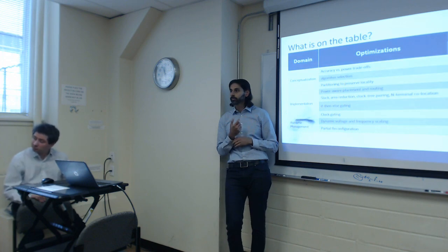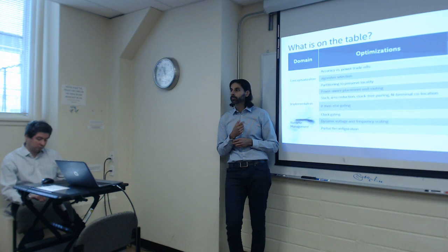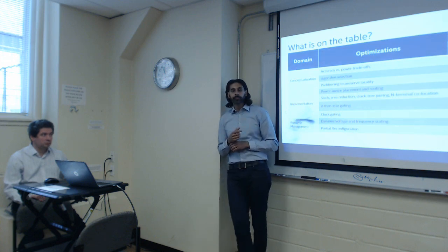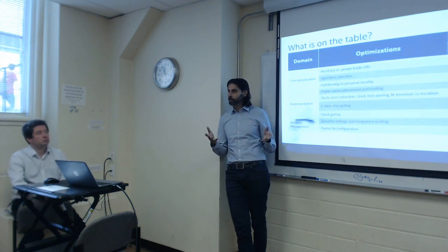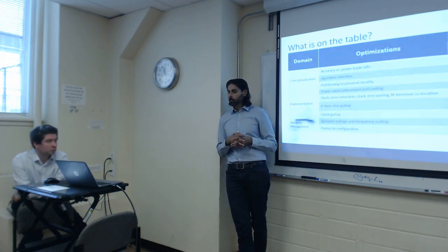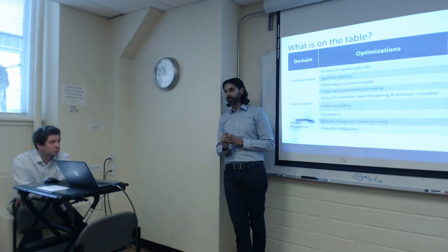Just out of curiosity, for EPE and FPGA, what's the estimate? Generally, what's the percentage difference? The Early Power Estimator is a standalone tool. It doesn't have any access to your RTL. So the biggest knob that impacts accuracy is the fidelity of the input.